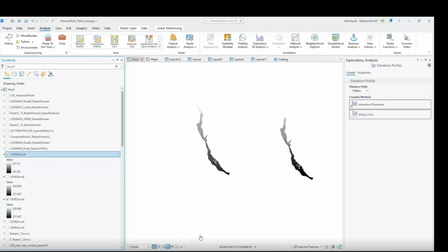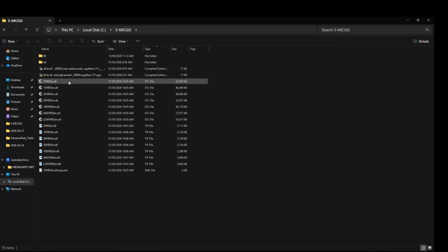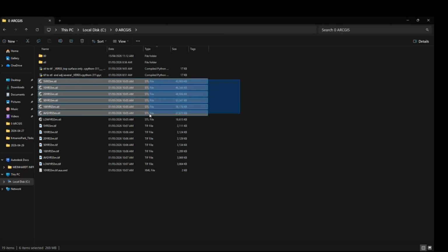What I think is, before starting a project, we should set up survey points for everything. Civil 3D has it, but Revit as a base does not. So when the file comes from the BIM team, they need to first check all the base points and survey points. The survey point should be the same in all the templates. I think that is one of the missing steps, because hydrology gets the file, then you use it in Civil 3D, but as soon as you transfer it to Revit, it's a different software and a different version. So the survey point should be the same in all the files.